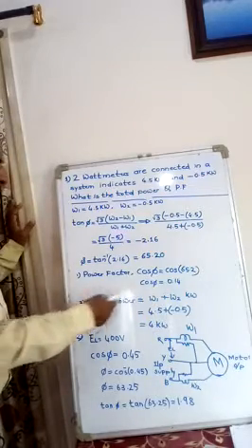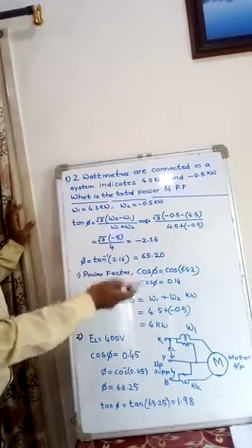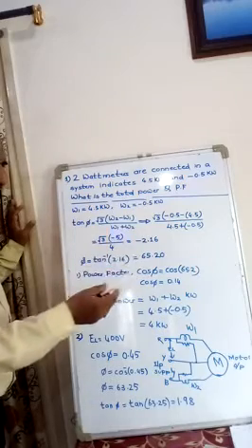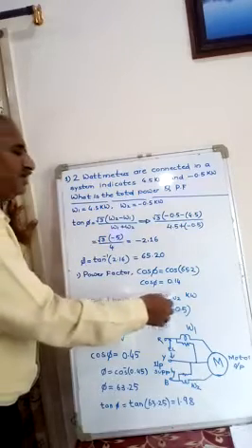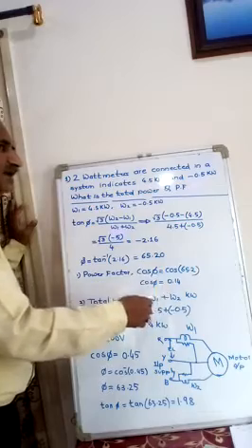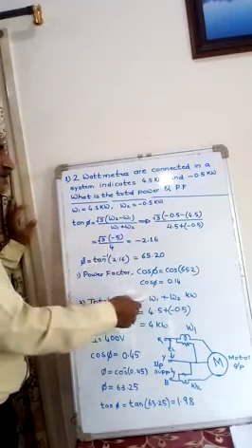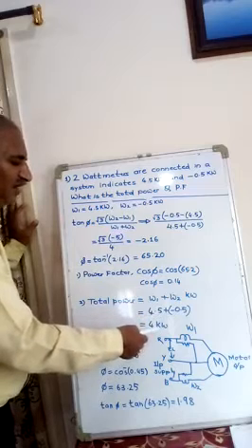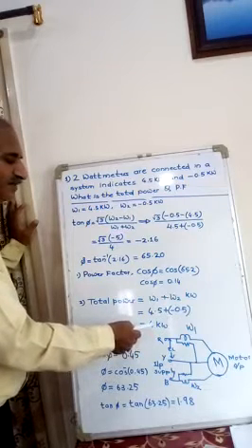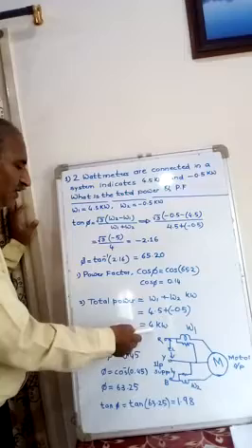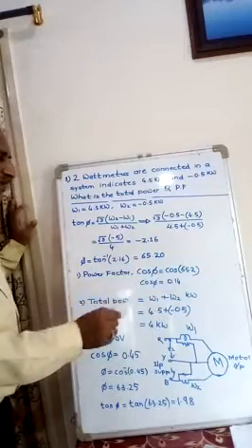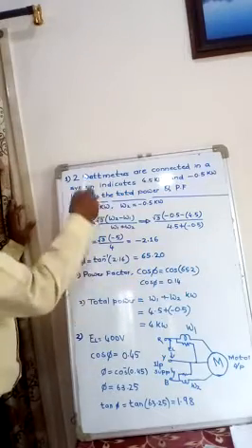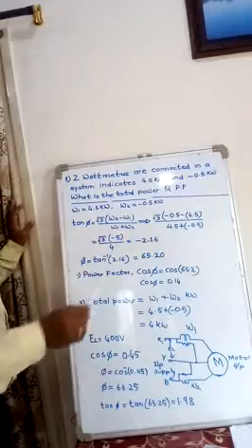Number 2, total power is asked. Total three-phase power, we know one expression, 3 times V_P I_P cos phi. If you know the wattmeter readings, three-phase power is also equal to W1 plus W2. You can add this. Then you get the final answer, 4 kilowatt. Total power is 4 kilowatt. Power factor is 0.14. This is one of the very basic ways of understanding the problem.